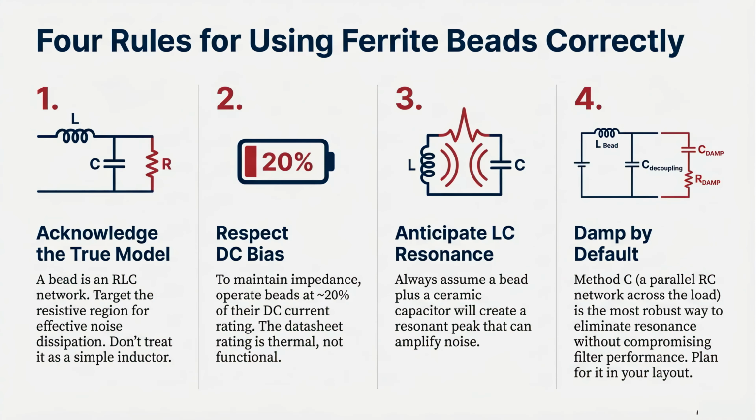no-filter baseline. Remember these 4 rules for using ferrite beads correctly. Acknowledge the true RLC model. Respect DC bias by operating at 20% of the rating. Anticipate LC resonance, and damp by default, preferably using Method C.